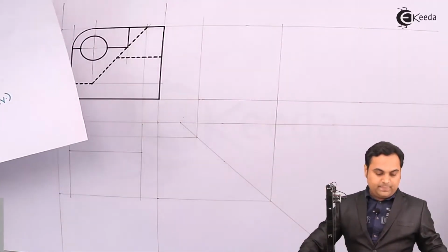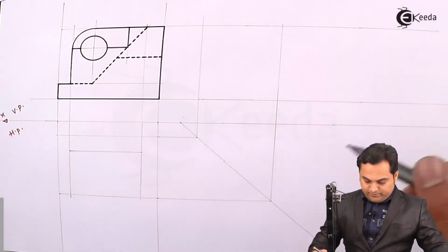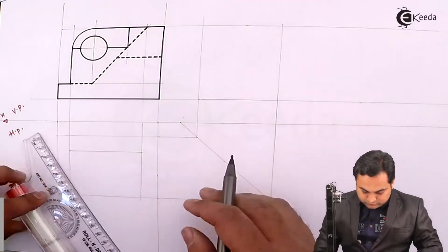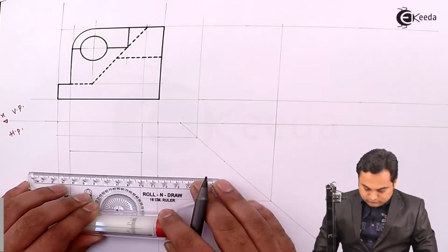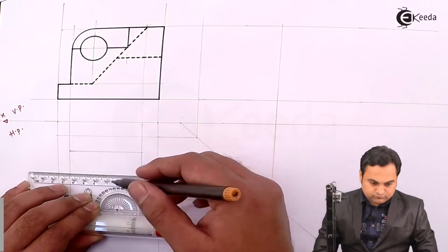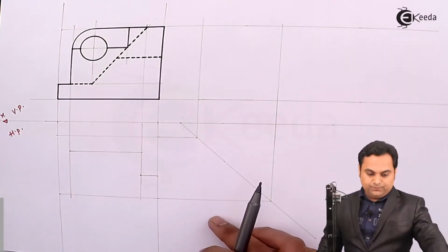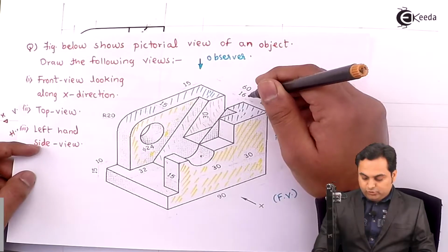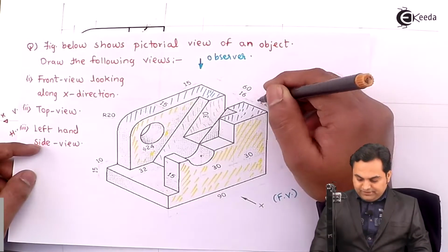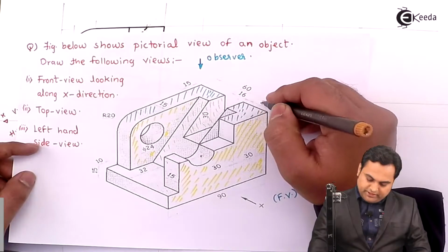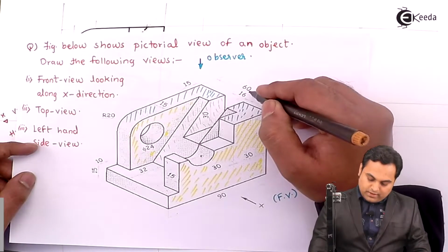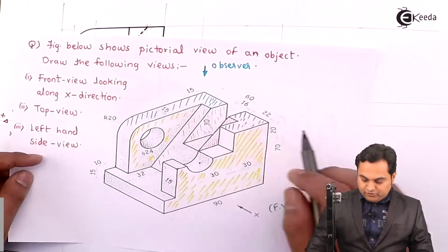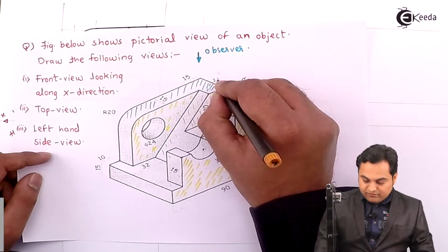So next I'll measure 22 mm width here, and then after measuring this 22, there is another distance of 16 mm, and when I add 22 plus 16, that value will be 38 mm, and from 60 if I subtract 38 mm, that is going to give me the value as 22. So even this portion is having width of 22 mm.